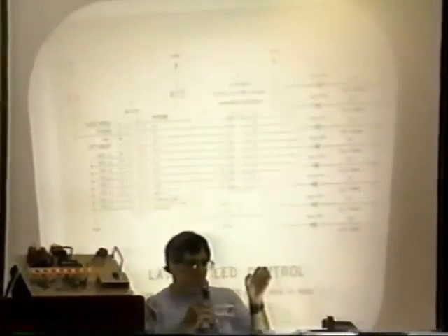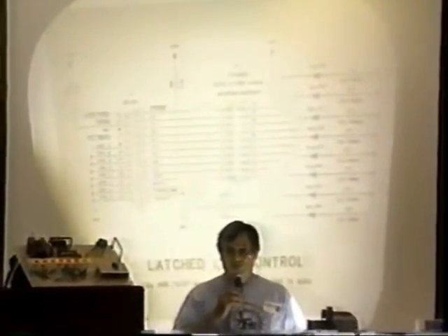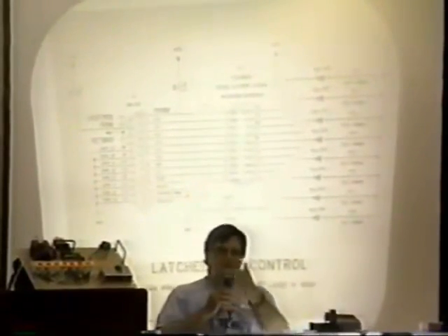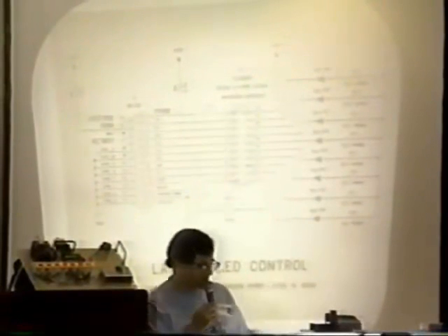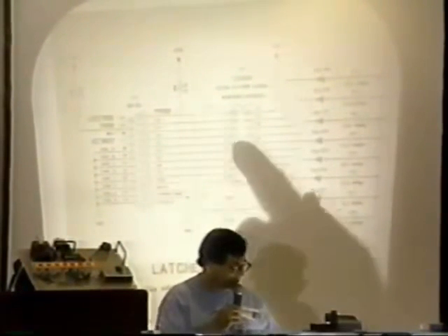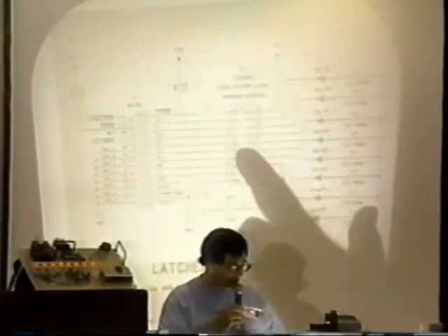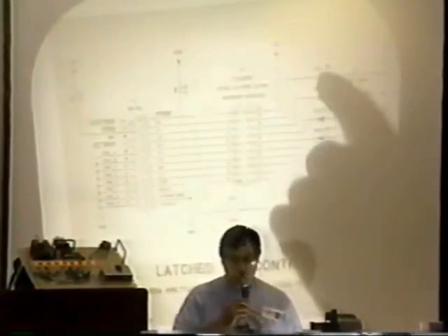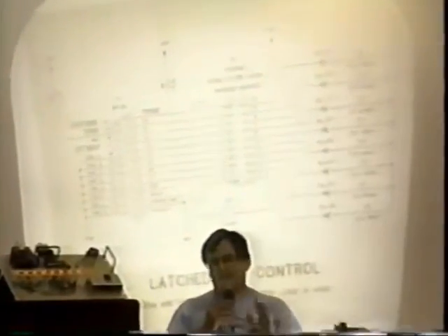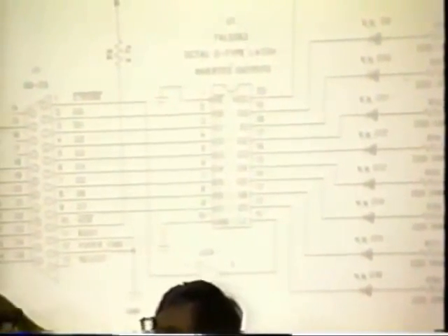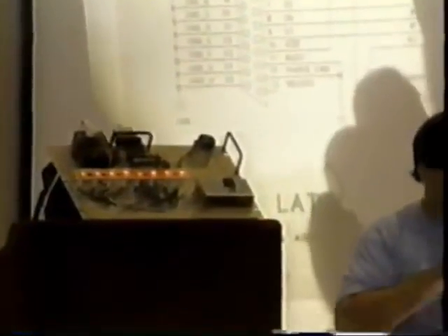Unfortunately, if I put 8 LEDs in the front of the room, I don't think you would see them very well with a camera blasting and with these lights on. So I put a little buffer in the circuit, and instead of using LEDs, I'm going to cheat. Everything's exactly the same as it would be, but I'm cheating because you wouldn't see it. I have these lights up here, and they're running on 5 volts, and I hooked up this little circuit that makes the little teeny weeny voltages coming out of your computer a little stronger, and that's called a buffer.